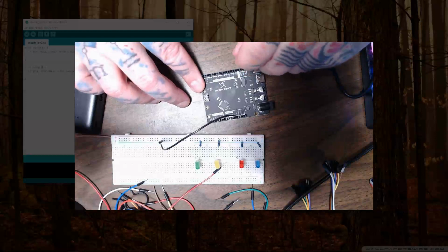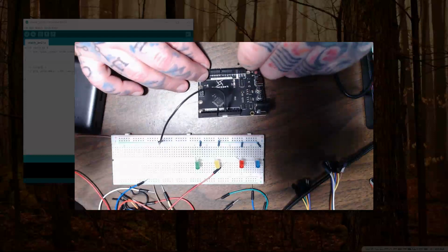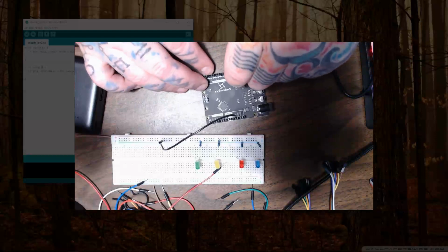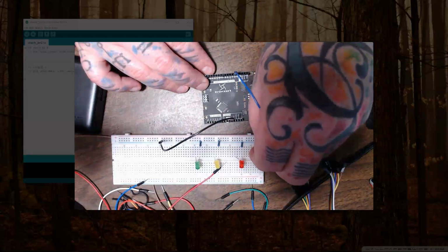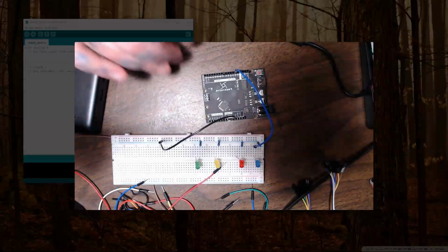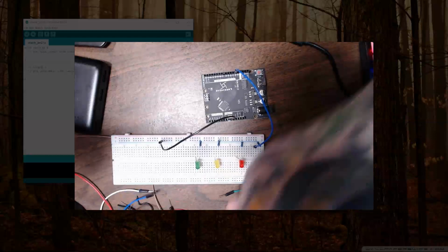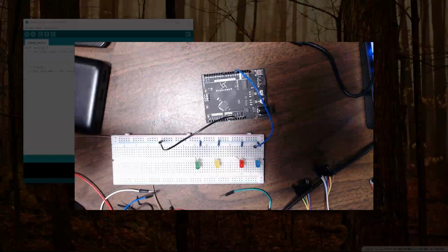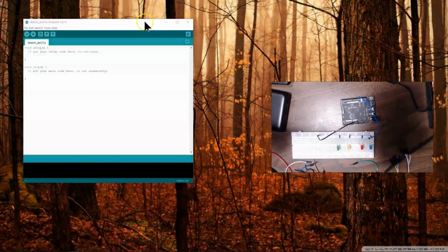Doesn't fully matter, and I will just go with a different one than we did in the simulator video. I will go with pin 12. So I'm just trying to line that up, pin 12 going in, and then we're hooking it up to the row so it goes to the actual anode. Now, if I was to plug this in, nothing's going to happen. We don't have a program loaded. We've done nothing else with this. So we will just go back. I'll check this down, and now we will go to do some more code work, leaving a little video down there.